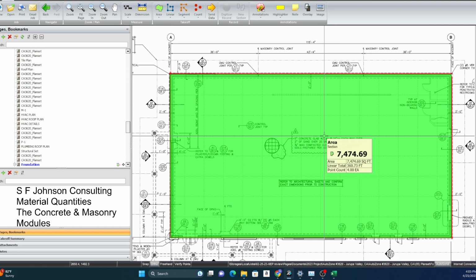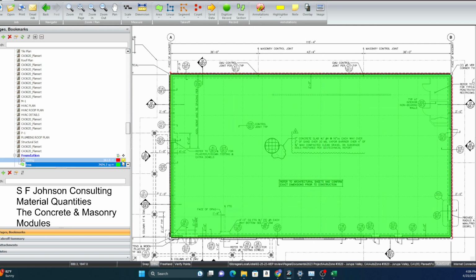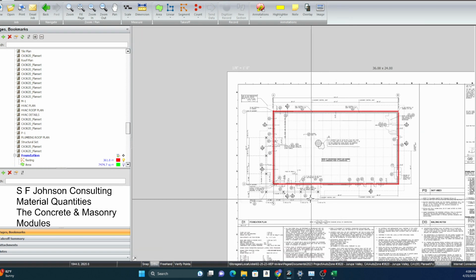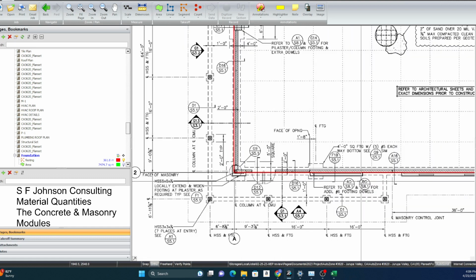And so just say, for instance, it's a 6-inch instead of 5-inch. So if it's a 6-inch, we change that 6-inch into feet. So basically it would divide that 7,500 square feet in half. So we'd have half of that, but that would be cubic feet. And you divide that by 27, and then you have how many cubic yards. So that's how many cubic yards of your slab on grade. And we have to figure out how many cubic yards for our continuous footer.